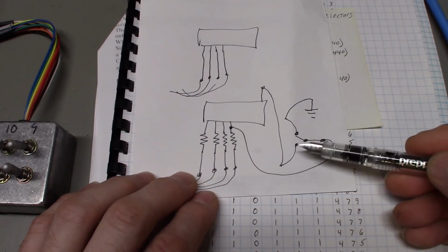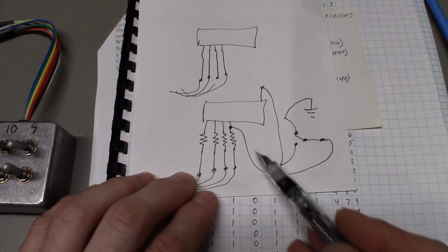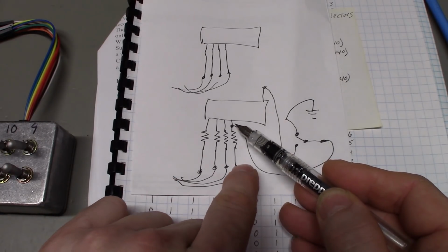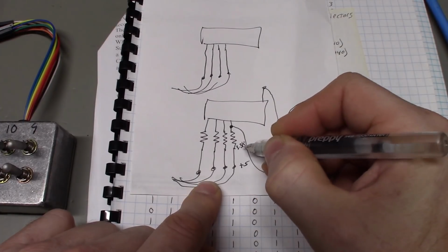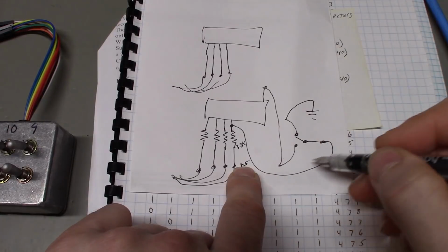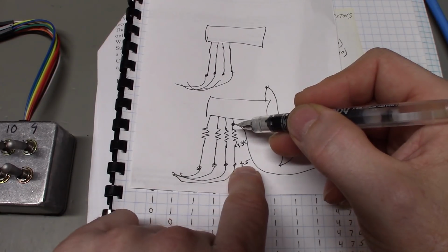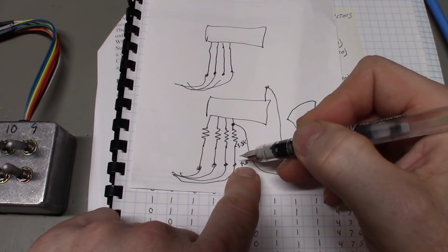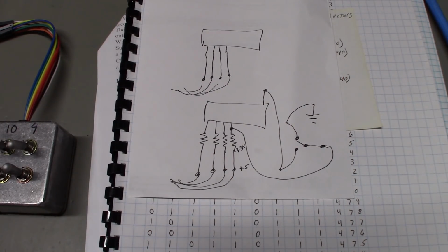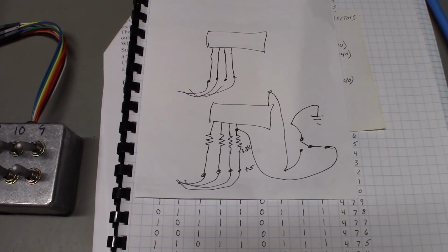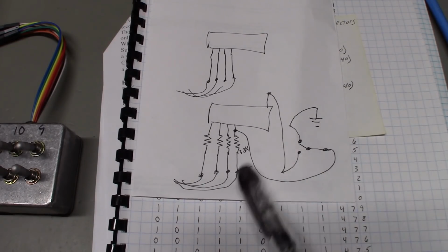So now if you were to take this toggle switch, just as I have it in the picture, the toggle switch is in the grounded position. Okay, so that's now supplying a ground to this pin. But if the channel selector switch was applying, let's say, 5 volts positive here, there's still a 3.3 K resistor isolating that 5 volts from that short to ground that you've attached. So you're applying a binary 0 here. The channel selector is trying to apply a binary 1 by applying voltage here, but it's not a dead short. No magic smoke comes out because there's a 3.3 K resistor here preventing that direct short. That's all you're doing with the toggle switch. And that's also why you have the resistor there, to prevent the magic smoke from coming out. So the ground and the voltage sources never come in contact directly with each other.